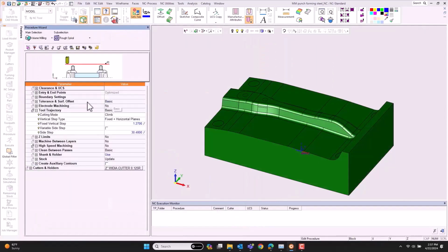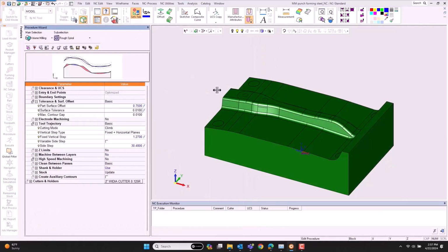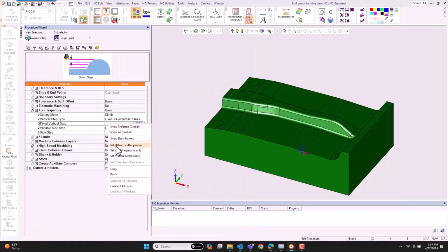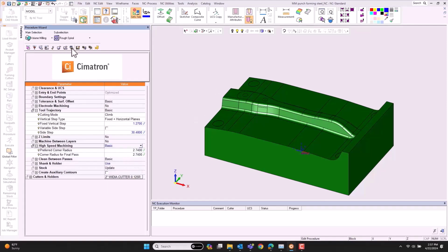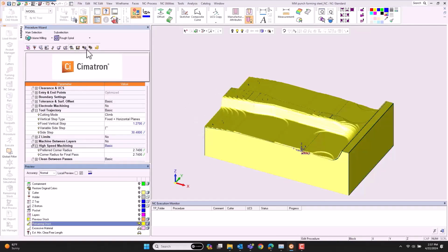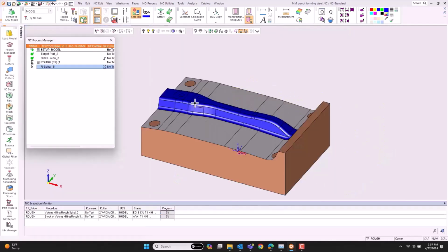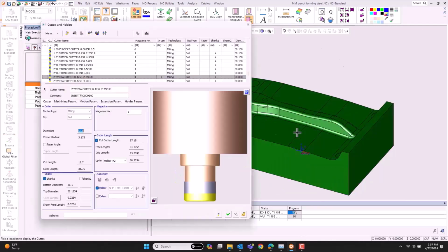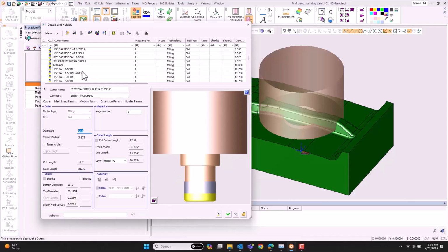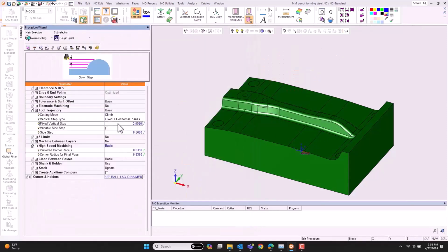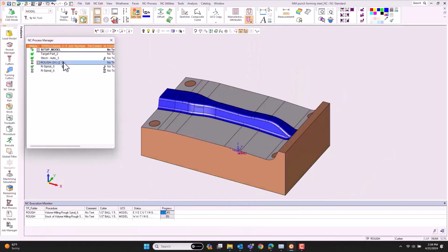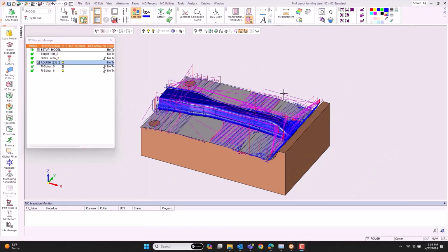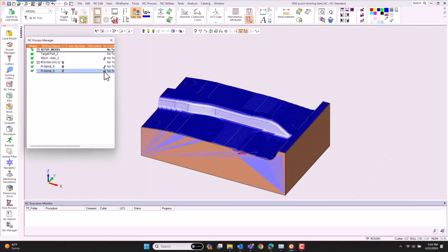Further along the way to go with this would be to do some NC. So here I've pulled in my tool library, and I'm working with one of those different form stations, setting up what I want for my offsets and my step overs. In this case, we're doing a rough cut, a rough spiral. And as we do it, it's going to know where the stock is, and it's going to target just that stock. So if I come back in here with another rough cut, it'll cut just that remaining stock.